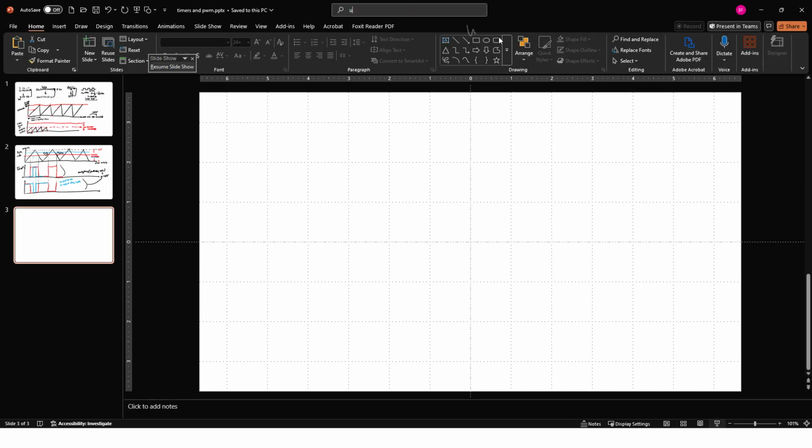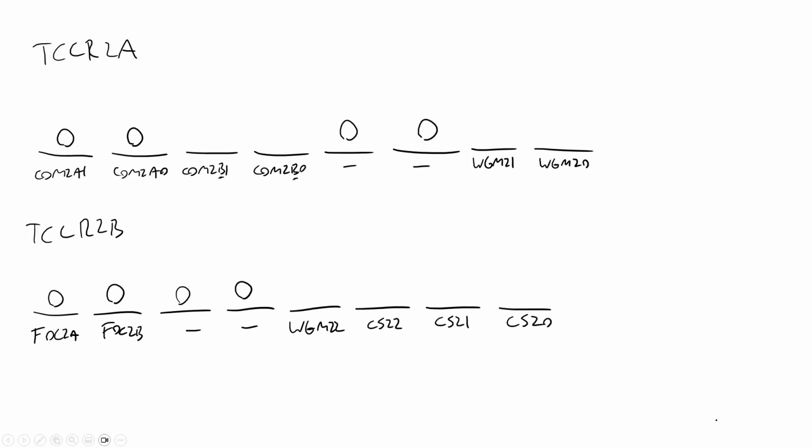So remember, whoops, it doesn't like when I write at the top, so let's do that somewhere else. The WGM, or waveform generation mode bits, to set to phase correct PWM mode, I want those set to 001. Remember that came from the table we looked up in the datasheet. It's just a little weird because those bits are split across the two registers. So going from left to right here, I'm going to fill out the most significant bit first. That's WGM22 down here, so that is 0. And then fill the rest in here, 0, 1. So that was for phase correct PWM mode.